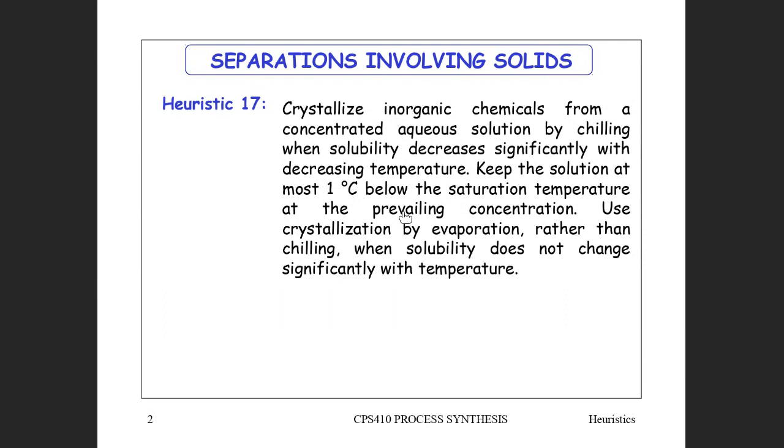As you're cooling it down, more and more salt is coming out of solution and forming crystals, and you slowly bring down that temperature until eventually you've saturated out most of the salt in the form of the solid crystals. Use crystallization by evaporation rather than chilling when the solubility does not change significantly with temperature.